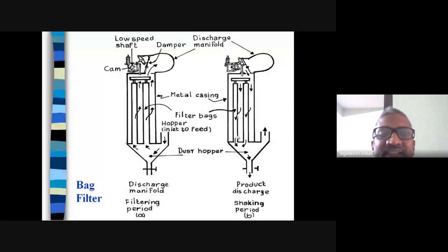The limitation of this particular mill. The limitation in this case is that you must have the material present in the fluidized state as an inlet. You are not going to separate it as a powder. You are going to separate the powder which is present in the fluidized state. That is the only limitation. If you directly take a mixture of powder and pass it through, you won't get separation. All the powder will be blocked. You can separate only solids from the air. That is actually the limitation of it.